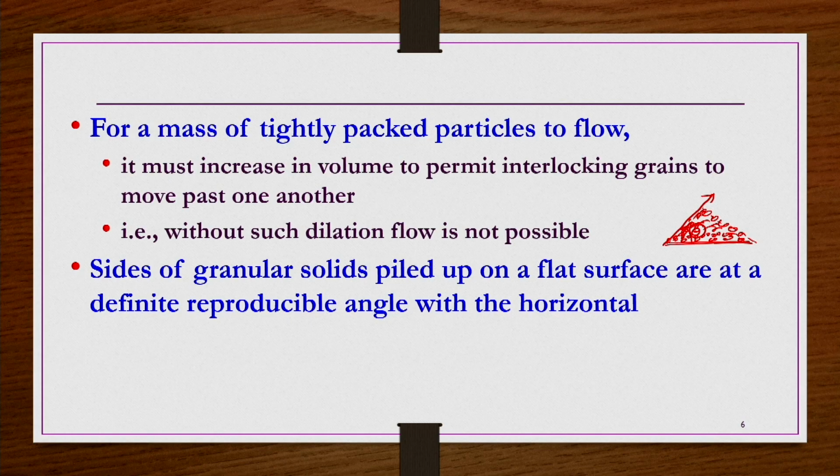And not all materials will pile up with the same constant angle. Some material, if you pour on the surface, you may see that they pile up spreading more, with less height, so that this angle is also less. Here in this case the angle is less. So, let us say here theta 1, and here theta 2. Theta 2 in this case is less than theta 1. Let us say the second material is rice and the first material is wheat.